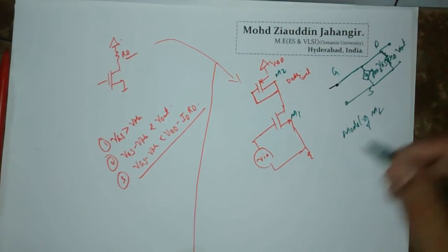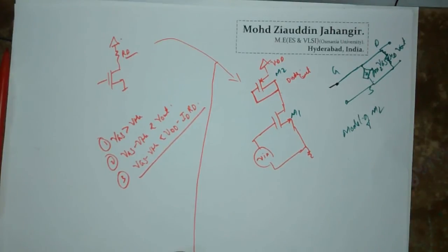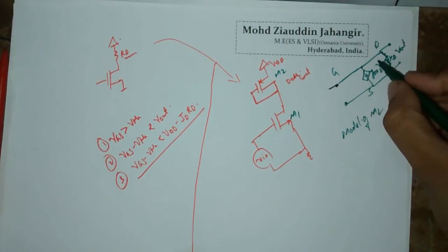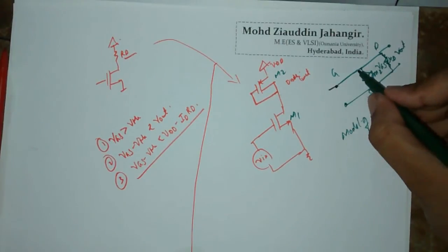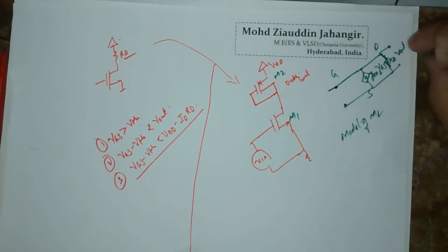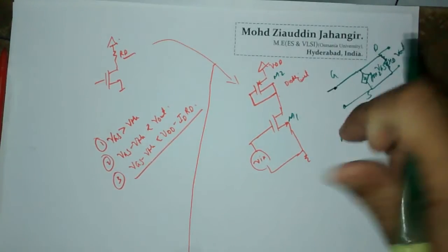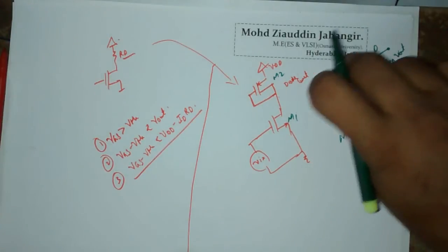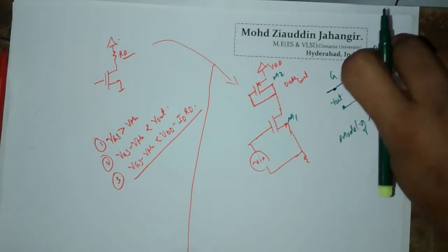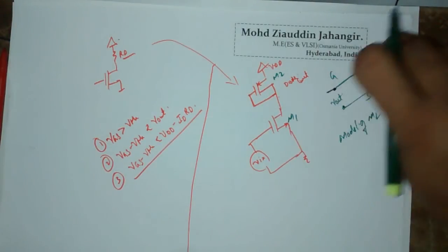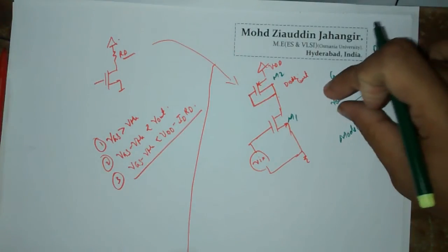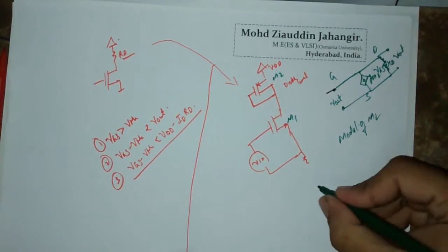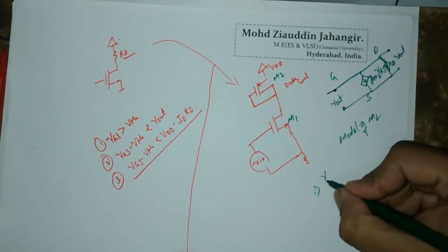First of all, what is VGS? VGS is the voltage between gate and source. Once you have connected gate to drain, this output voltage is going to be this voltage as well. Why? Because everything is in parallel, so the voltage in a parallel circuit is going to remain the same. So your VGS will now be equal to your Vout, and even this is your Vout.